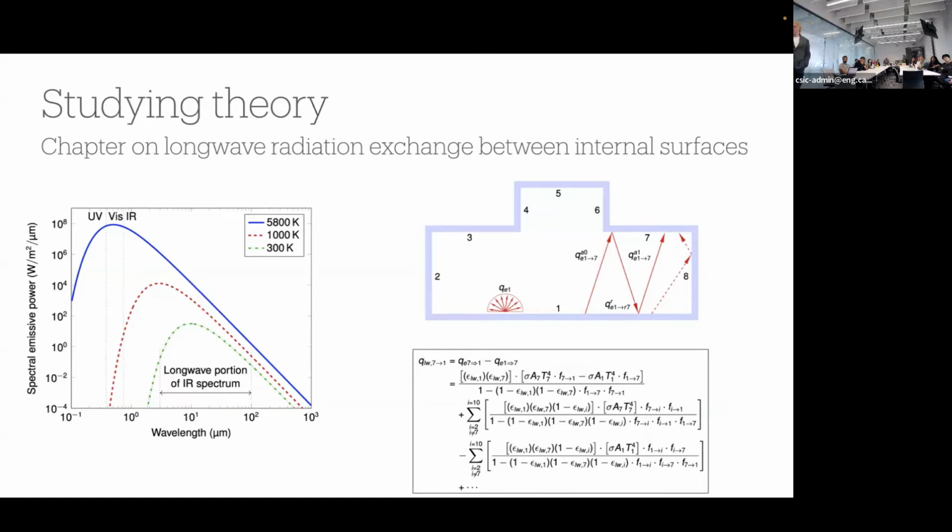And then you can see from that radiation view factors between individual surfaces are necessary. So then this is only used in certain tools, but then the reader of the book will use the simulation tool they've chosen and see what options are available in that simulation tool for calculating these radiation view factors. And then realize what parts of that equation they need to provide data input for, and what is default.